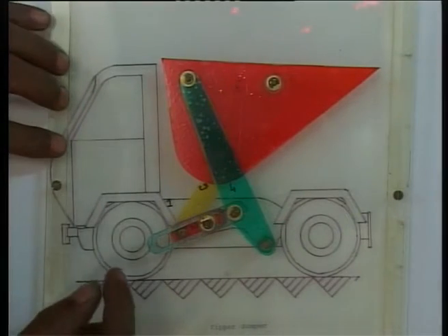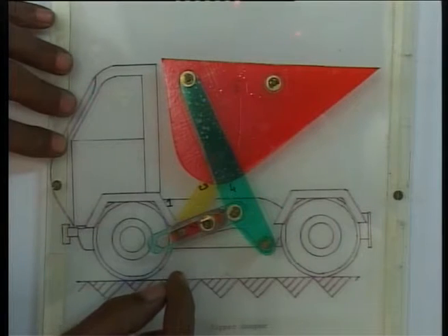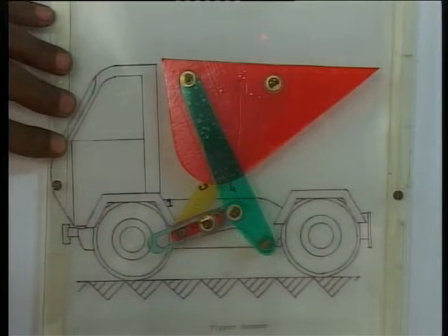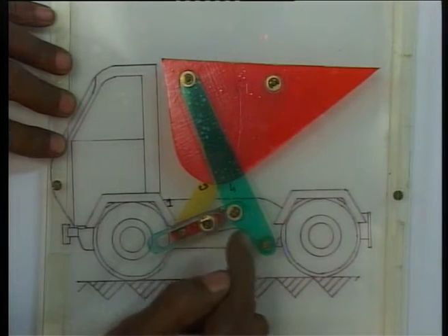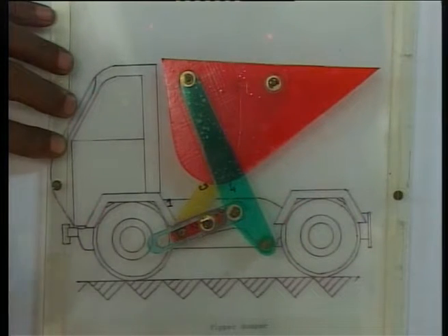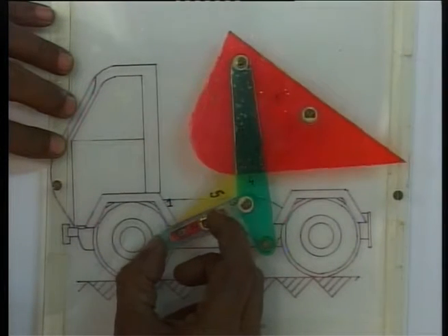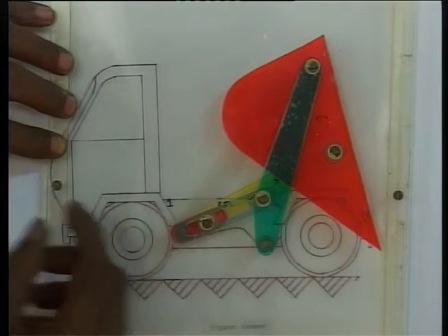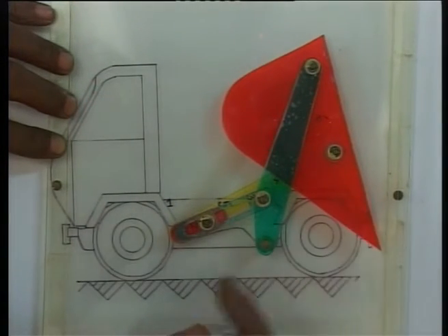We shall demonstrate it by 3 models of earth moving machinery or tipper dumper having 1, 2 and 3 degrees of freedom. Obviously, in a planar mechanism we can have at most 3 degrees of freedom. As an example of a single degree of freedom mechanism, let us look at this model of a tipper dumper. This has 5 moving links and 1 fixed link, which is the body of the dumper. Here the input motion is provided by this hydraulic actuator, which tilts the dumper bin.